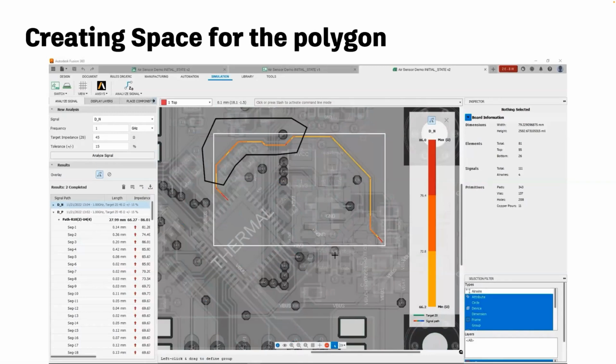So you can see right there, those are areas where the impedance has changed drastically because the geometry has changed. It's a violation of that first slide I showed you. What are the changes? Polygon is broken there, and we have components that are near the trace there, or close to it. So that's causing a change in impedance as well.